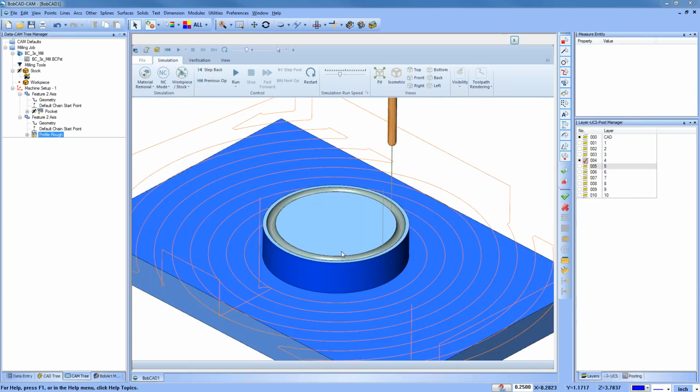Chuck asks, will ramp work on a non-center cutting end mill? I guess it's possible, Grant, because you have to look at the teeth and whether there's a pilot hole there. So it is possible that you could use ramp on non-center cutting tools. I don't know that I can answer that in all scenarios, but I think in some scenarios you could get away with it.